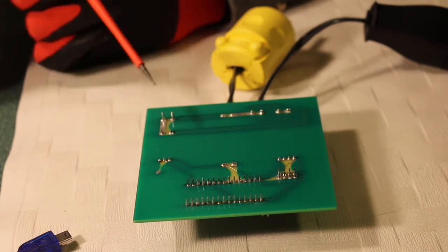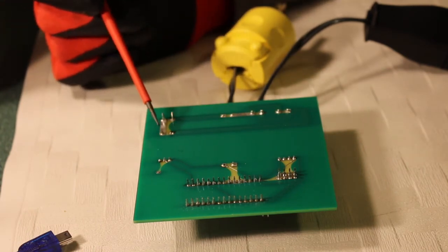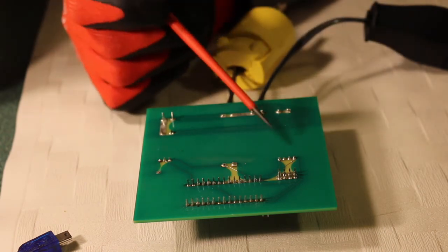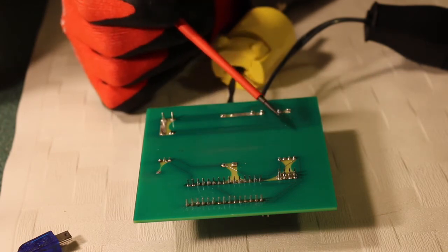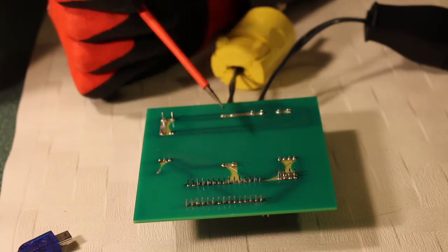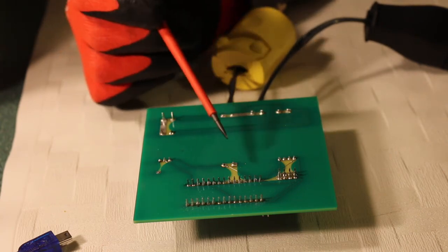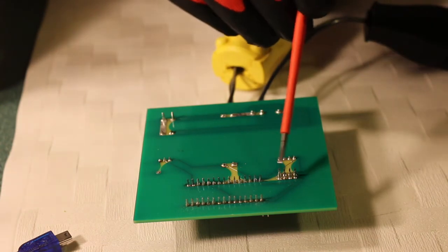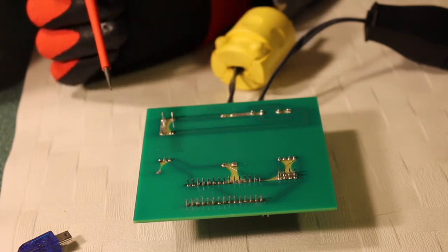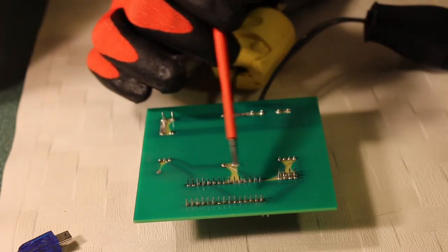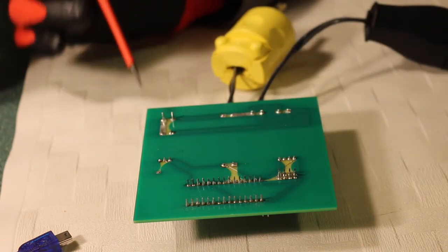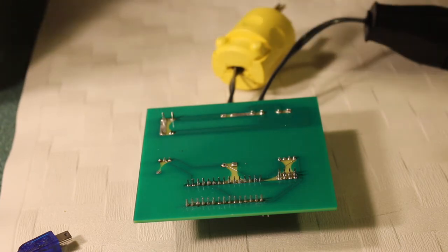So here's a look at the bottom side of the printed circuit board. Right here is the voltage sensor, which is measuring the parallel voltage at this node. Over here is where the current sensor is, measuring series current. In between those is the 120 to 5 volt step-down converter, powering all the small electronics on the board. These 8 connections right here are the pins for the ESP Wi-Fi module, which is communicating with the server and the Arduino Nano, which is all of the rest of these connections right here. All these connections have been soldered, and the PCB is complete.